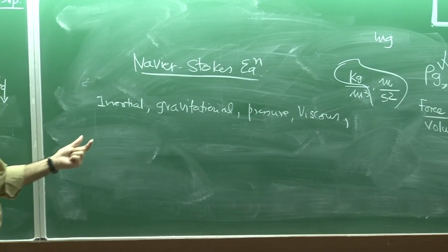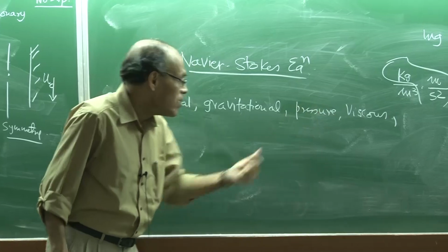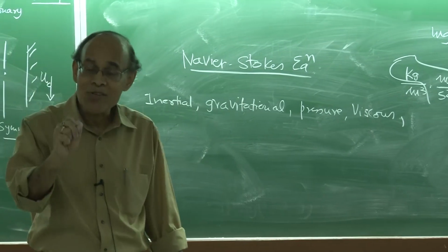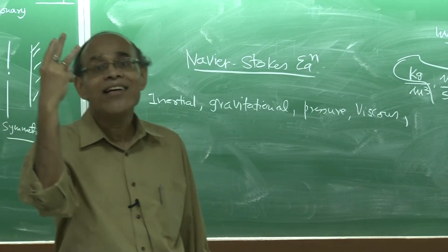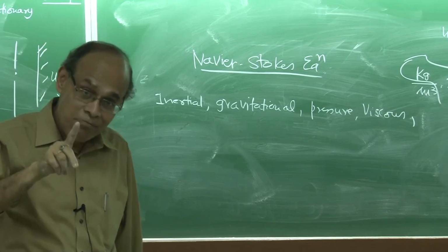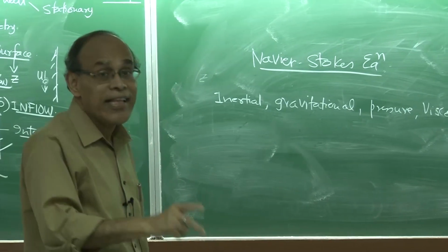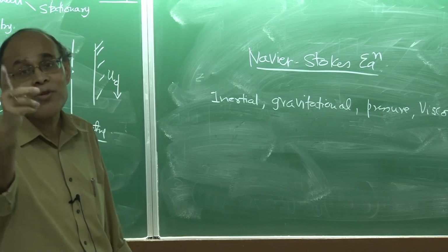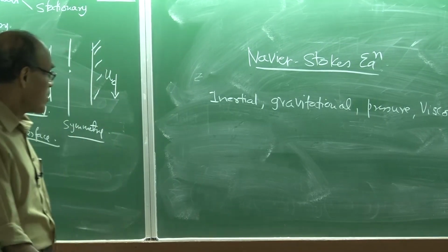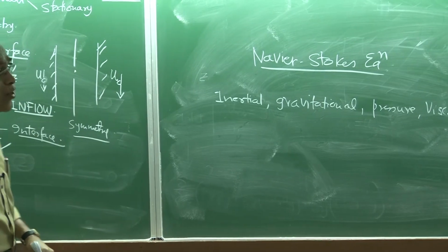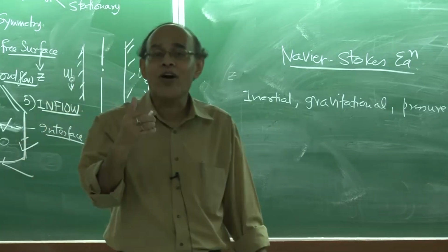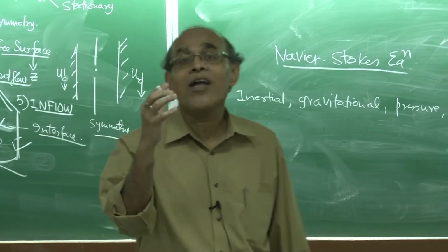So, therefore, when you use 4 terms and express the equation in the dimensionless form, you will find out that we are going to generate 3 dimensionless force ratios. So, we will have 3 terms characteristically. They are going to be force ratios, and the 4th term is going to be unity, which is also dimensionless because all other terms are dimensionless. So, in that context, the force ratios are basically what we call dimensionless numbers or dimensionless groups.